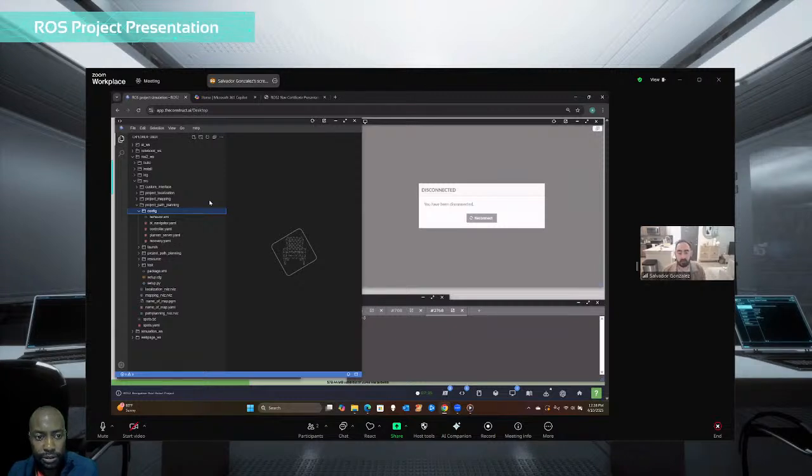Then there is another part, the controller, which does this on a smaller scale. It takes into consideration the sensor data and creates a cost map for barriers that it knows about and barriers it does not know about. It readjusts how it plans based off of these new obstacles. This looks like an aura of decreasing darkness from the obstacle, and we can adjust those parameters by things like the size of the robot.